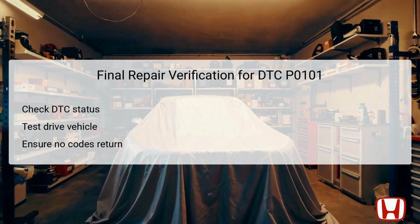After repairs have been completed to address the cause of DTC P0101, it is critical to conduct a final verification process. This begins by checking the status of the DTC, confirming that the code has been cleared or is no longer present. A test drive should be performed to simulate typical driving conditions, allowing the PCM to re-evaluate sensor performance under load and in different scenarios.